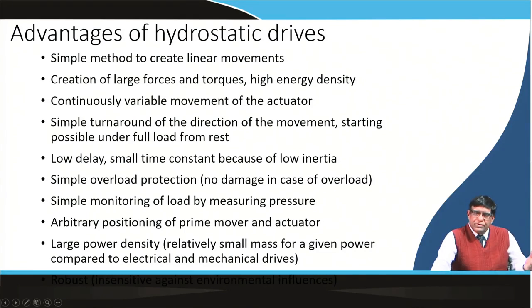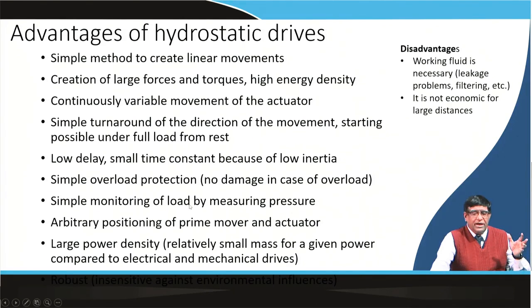A simple turnaround, so that we can easily make it reverse, low delay, small time constant because of low inertia, simple overload protection, you can easily get it, there will not be any damage. But in case of an electric motor and all, in overload, sometimes the motor may burn and then it will be a very big problem. Similarly, arbitrary positioning of the prime mover and actuator, wherever you want to stop, it is possible. Then large power density, that is the advantage of the hydraulic system.